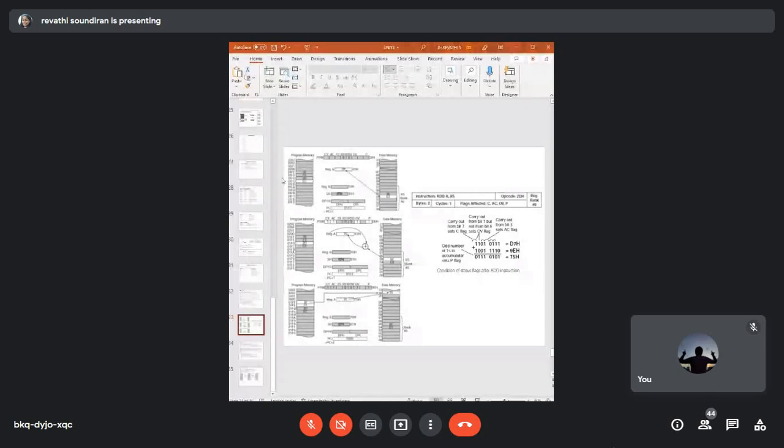So this add operation, if you see, is again a 1 byte operation. Okay, the opcode for the instruction is 2D, which is present in the next memory location, that is your program counter, 01FD. Okay, so 01FD is now under operation. So now the opcode 2D is going to take the content of R5. So we are supposed to add the contents of R5 with the accumulator value.